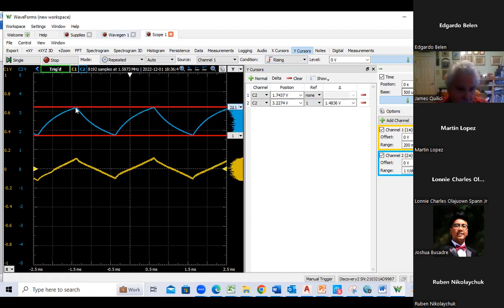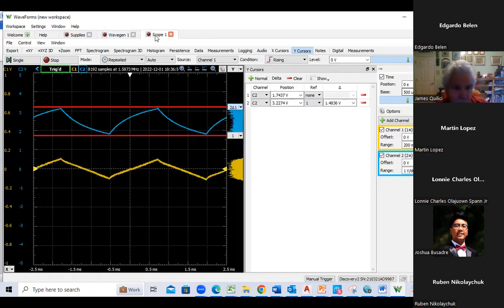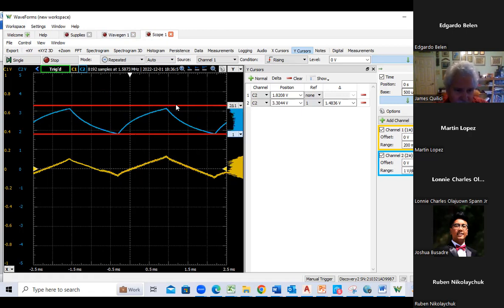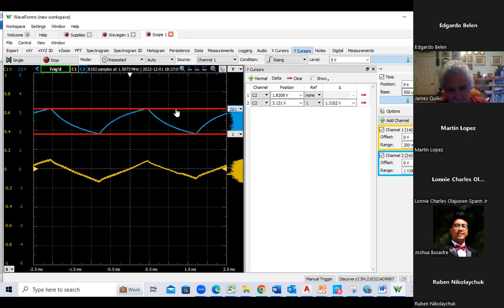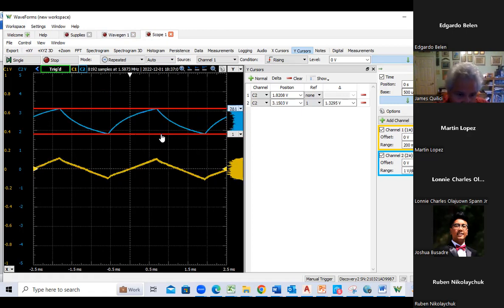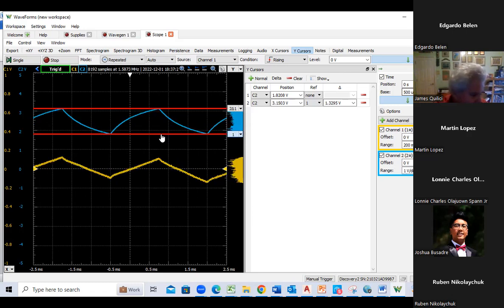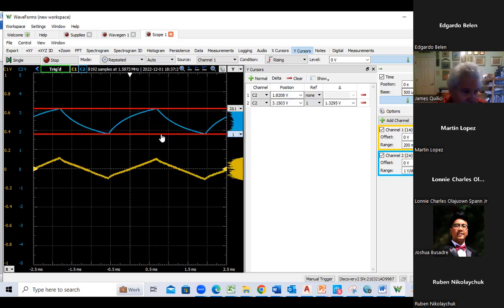I'm going to go to 400. Let's make a minor adjustment here. So that's 1.31. I mean, you can sit there and dink around with the placement of the bars, but that's essentially where its 3 dB point is, somewhere close to 400 hertz. So yeah, capture that and then go back and look at what your SPICE told you and see if there's any correlation. Comment if they agree or not.